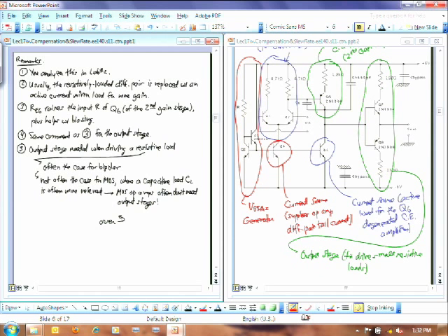Okay, other thing to recognize here is that RE6, this resistor right here, which I guess I'll label RE6, that's emitter degeneration for this second stage Q6. Why are we doing this? Why do we emitter degenerate this second stage? I mean, isn't that just hurting our gain?